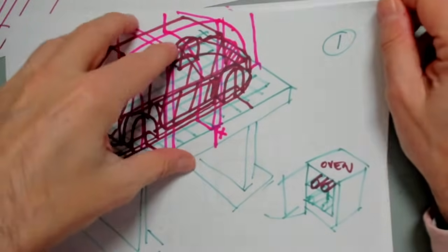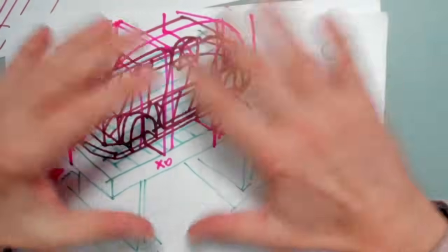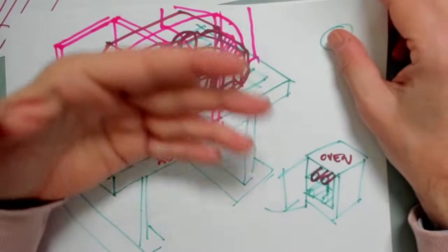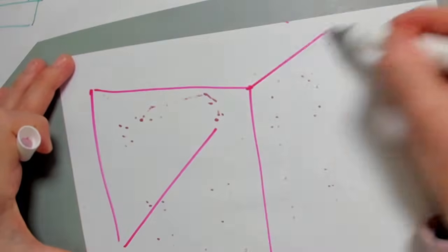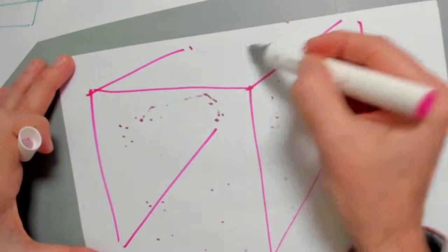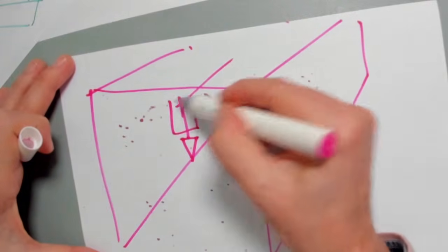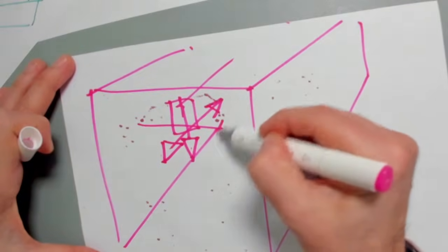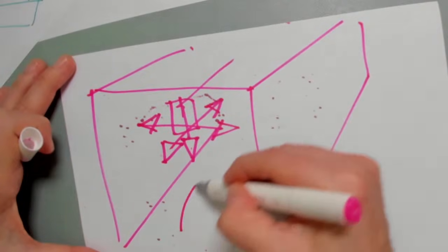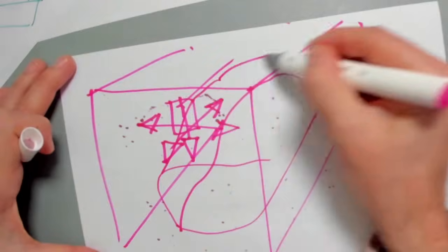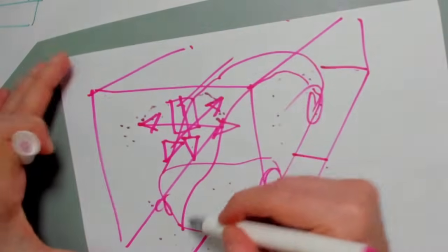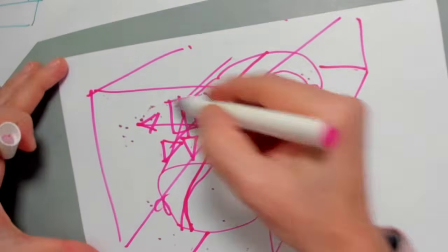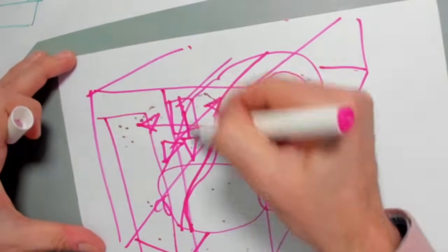But when we choose one and decide what modifications, then we go back to the Alias model and mill in full scale. The full scale is done with the milling machine. The milling machine is very big. It's a big room with a machine that has a point that is mobile in every axis. You have your big chunk of clay in full scale there with the wheels. There is also a grid on the ground so that it's correctly positioned according to the center section. Then they close the door. Those are glass doors, so you can see what's going on.